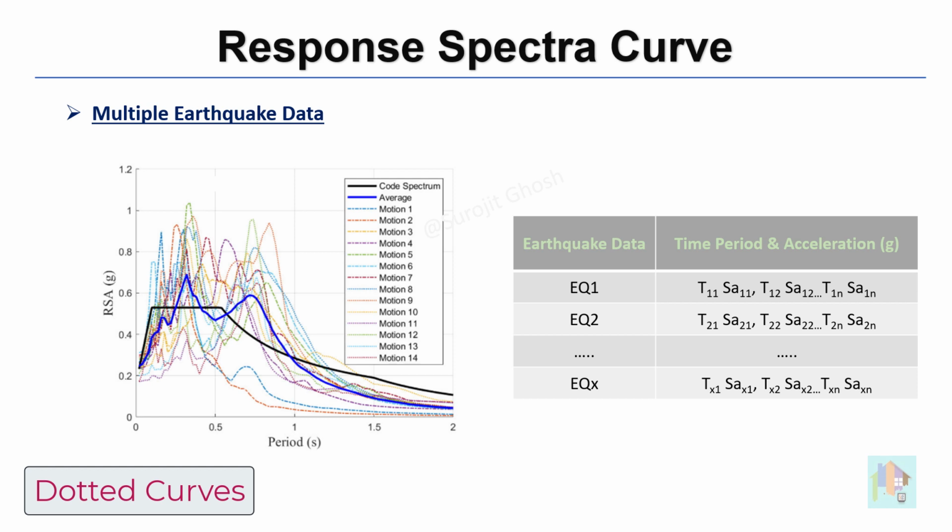We have considered mild to severe earthquakes, for which peak structural response should be different. Also, the same structure might respond differently when a different earthquake is repeated in the same site. If we use this graph to calculate the SA by G value of any structure, a slight change in natural period will lead to a large variation in maximum acceleration. This is not realistic, as we cannot even compute the natural period precisely.